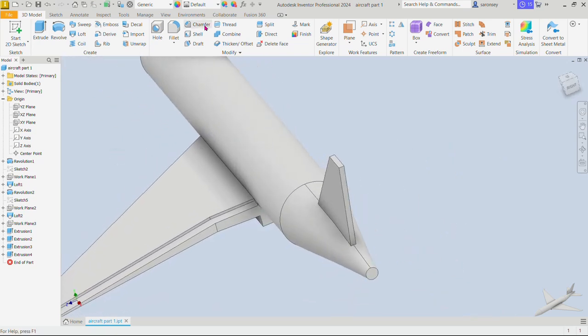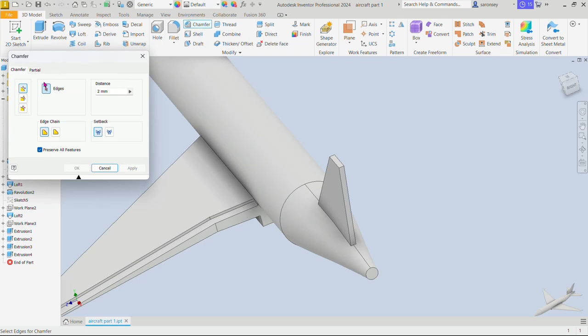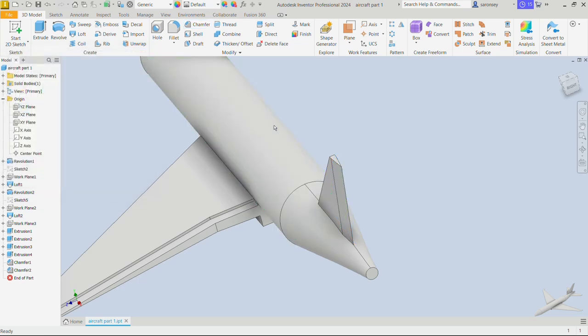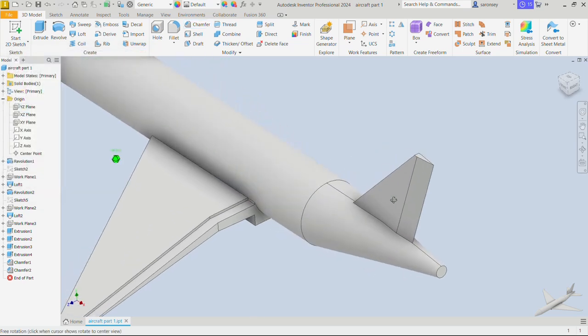Next, we would apply a chamfer, and so the chamfer command, but then we would choose the last option here that says two distances. And for the distance 1, we would keep it at 2000. For the distance 2, we'll keep it at 250. And we are left to select the edge. So we'll select this edge. The preview of that is okay. Let's apply. We'll do same also for the opposite edge and apply. Now we can close this. Let's see what we've done.